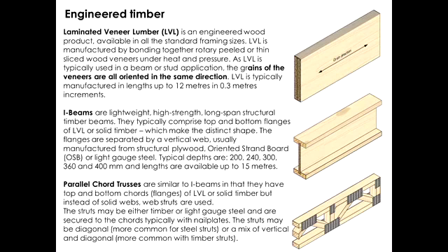structurally speaking, means that these are elements that can either work in compression or tension within a truss system, but we don't know which is the case. Okay? So some of these will work in tension, some in compression. So you can call them struts, but it's not structurally accurate all the time. So in a truss system, it's just better to call all the elements bars. So when there is no deflection and there are only axial forces, we're talking about bars.